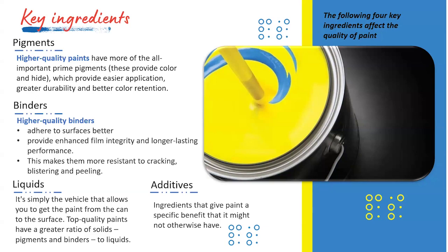All right, so let's do one more. How many coats are standard for a building exterior made of stucco? So that's going to depend on the condition of the building, how long it has been since its last repaint, and the color choice. So that's hard to determine. If you're using the same color, if you're not changing color, and the condition of the building is in decent shape, you would use a coat of sealer, a uniform primer, to help with the adhesion of your top coat. And you should be able to have one top coat.